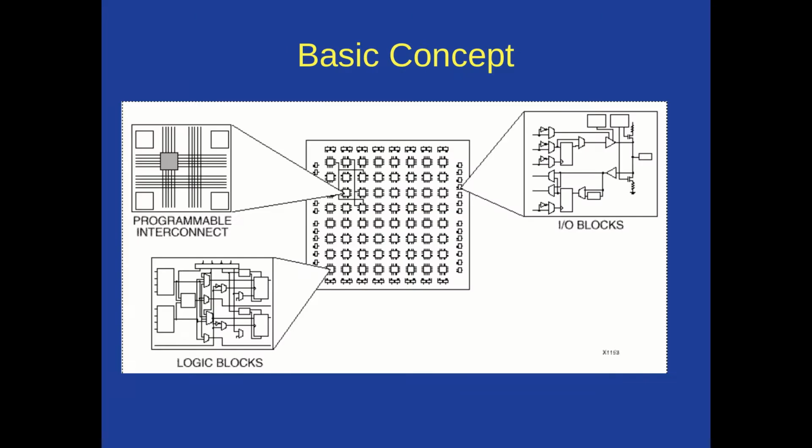And the basic concept inside, this varies from one processor to another, but basically we have a whole collection of these little programmable devices. And the specifics of that device, that's the secret sauce of each vendor. But it's something that has some logic blocks and some flip-flops and some multiplexers and a way to say, okay, I want you to take two inputs and tell me if they're both 1 and put out a logic 1 if they are.